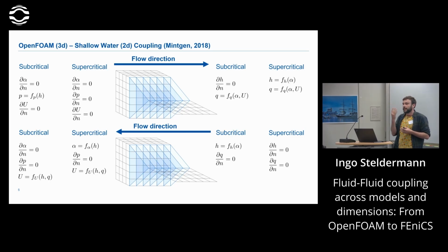Then we already have 4 cases that we need to differentiate at each coupling step. Essentially, in which of these phases are we? Based on that, we exchange information, build our boundary conditions, and we can move on. And to only iterate about 2 of these, what do they mean? Typically, they are either Dirichlet or Neumann type boundary conditions, unless we want to do something fancy. But in his dissertation, this is what he tried out, and it works well.